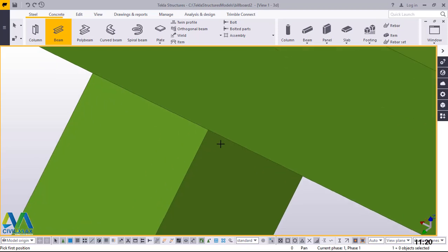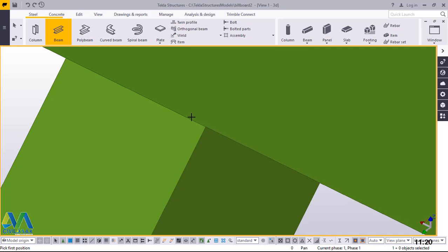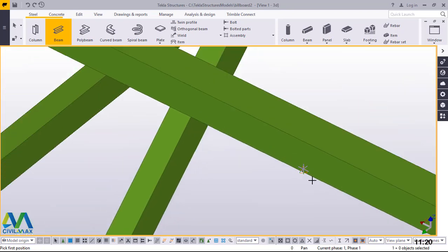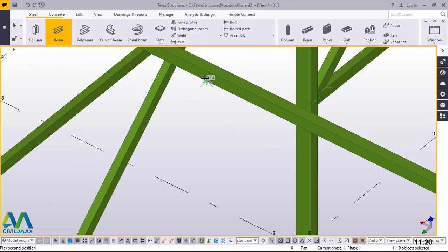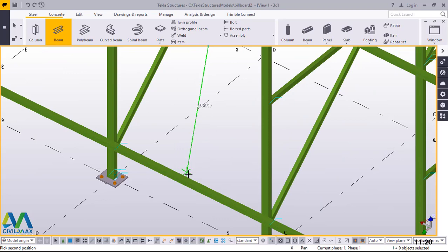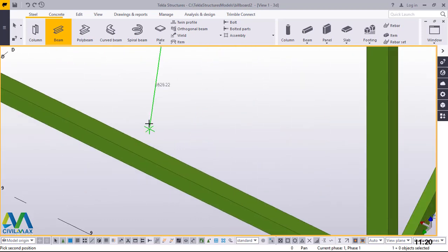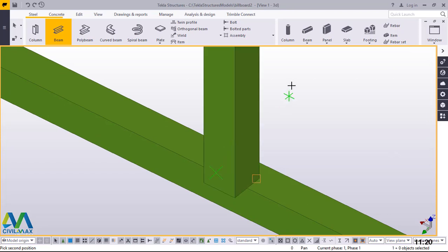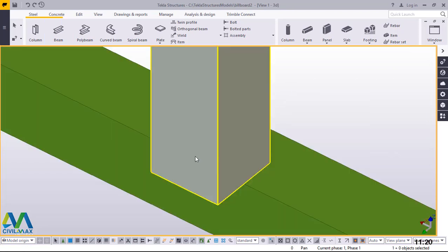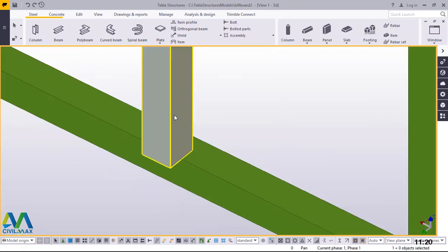We'll mouse over this part, mouse over that spot and move all the way to the bottom end there. Bottom end here and snap right there. Perfect. Now it is defaulting on this member, on this size, on this square hollow section.